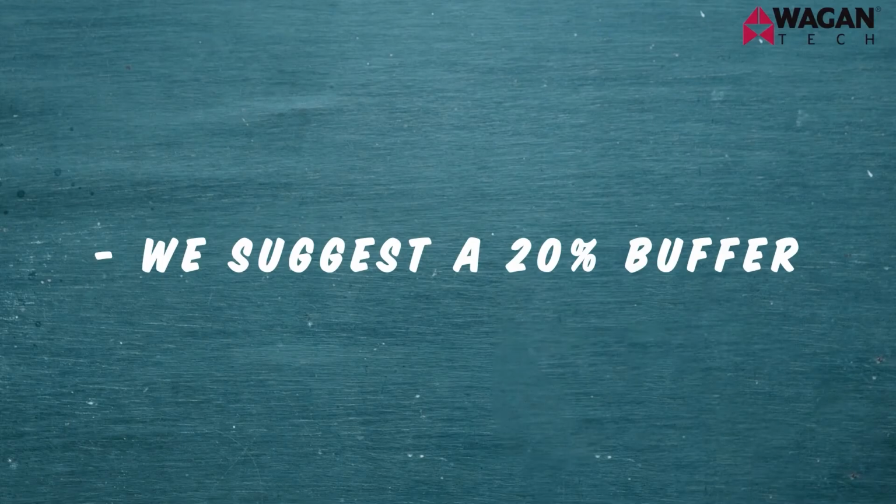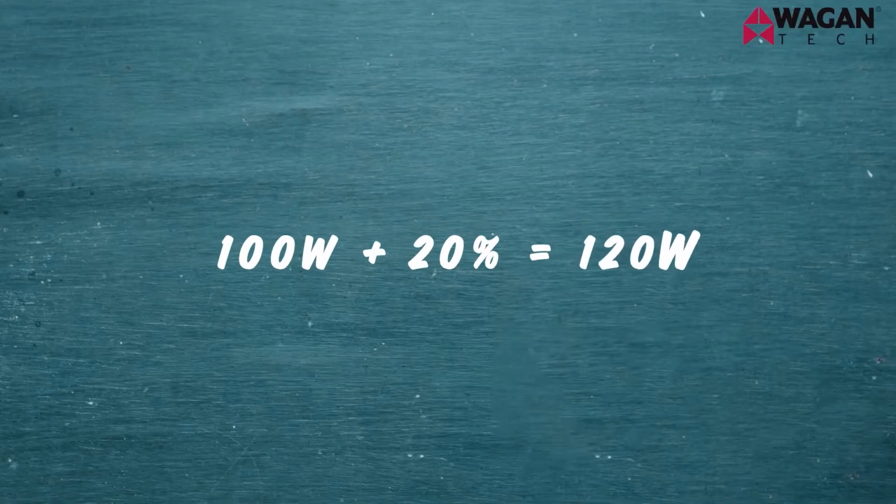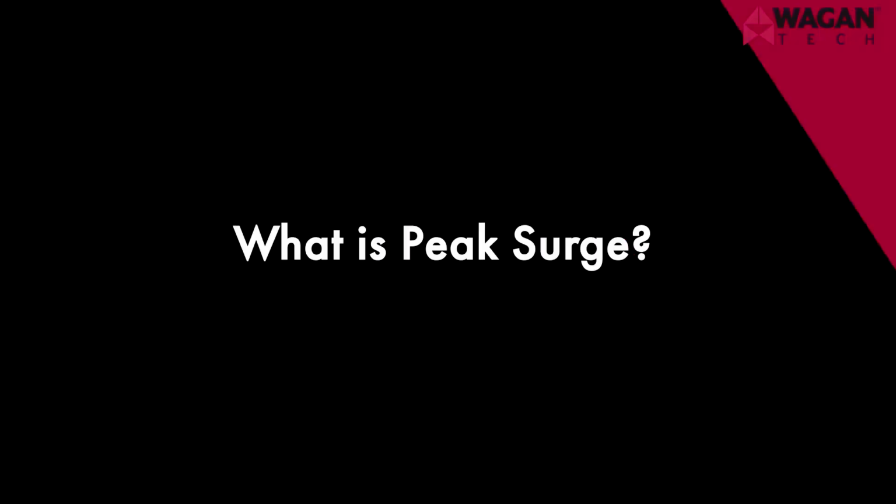So now you've calculated the 100 watts. That sounds good, but it may not be the ideal inverter for your needs. You'll be taxing the inverter if you get a 100 watt inverter and put a 100 watt load on it. So that's why we suggest a 20% buffer. So what you would do is take your 100 watts, add 20% to it, and come up with 120 watts. That would be a better fitting inverter for your needs.